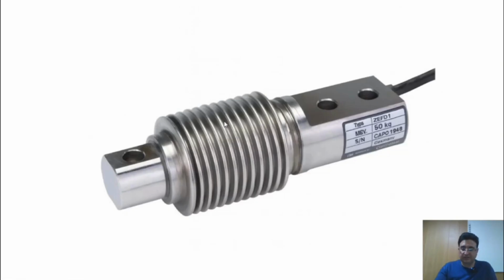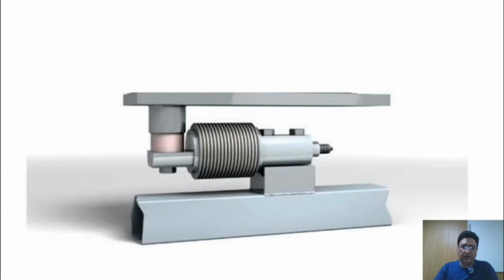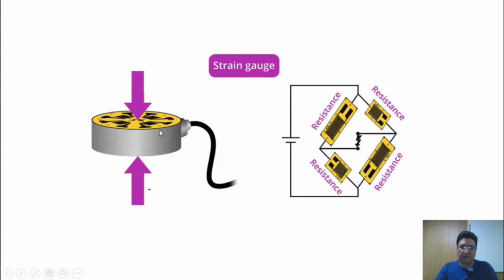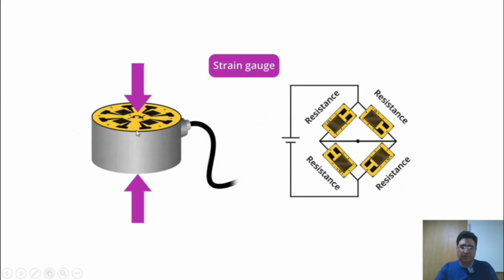The installation method for these bending beam load cells is similar to that of shear beam load cells. That is, we use mounting. A plate is placed above the load cell and another plate below it, and you can apply force to this section. The next load cell we are introducing is a type of compression load cell, but its shape is cylindrical, which is what we call this type of load cell.